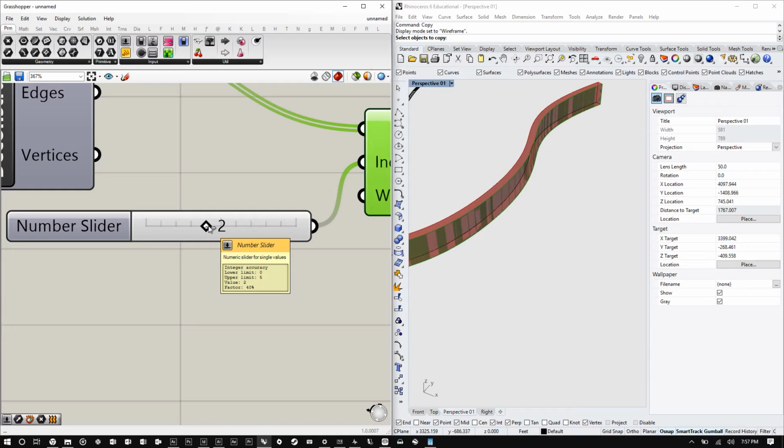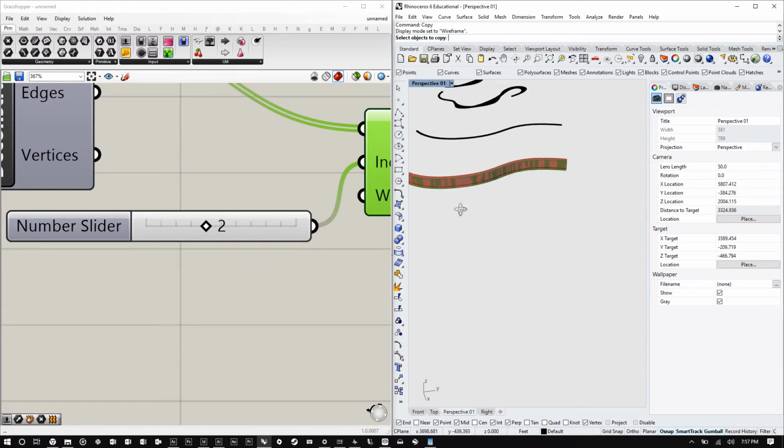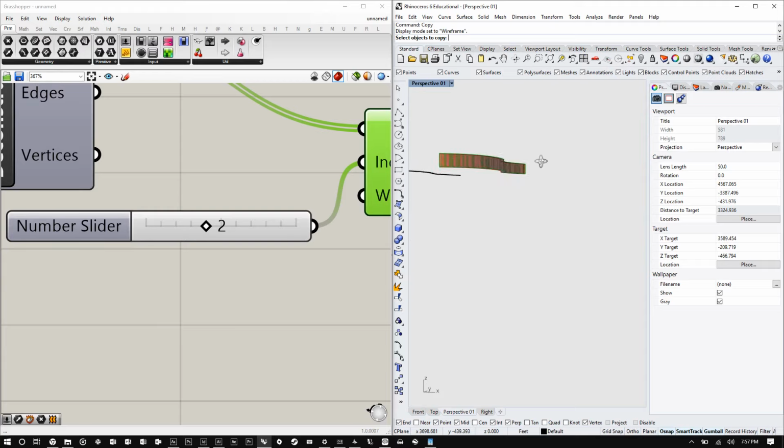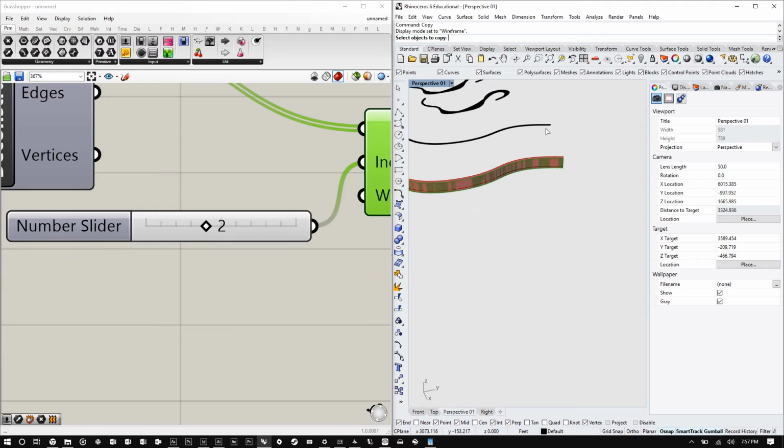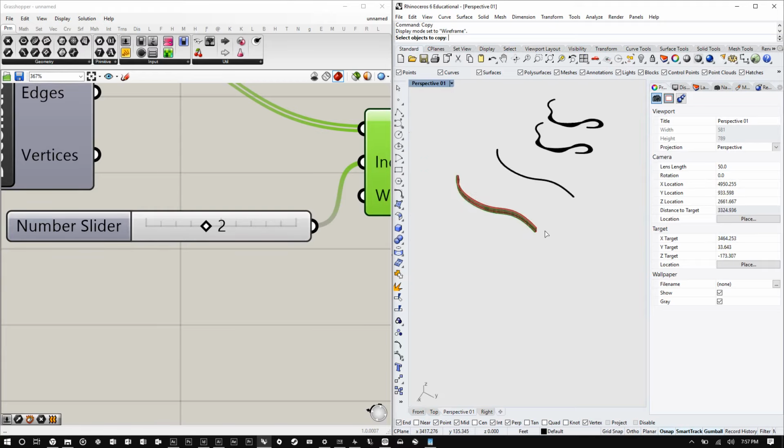But this is how, for example, if you're doing a building facade and you wanted to create windows and panels, you want to grab a specific surface and manipulate that surface. And all of those edits will work their way through. So in this case, let's do that. We're going to divide it a bunch of times to create our panels. And then once we've done this, we're going to close the session.